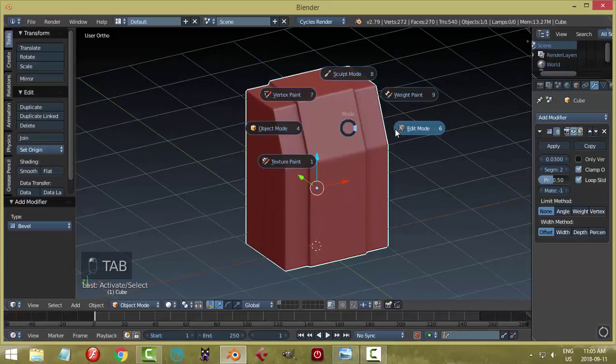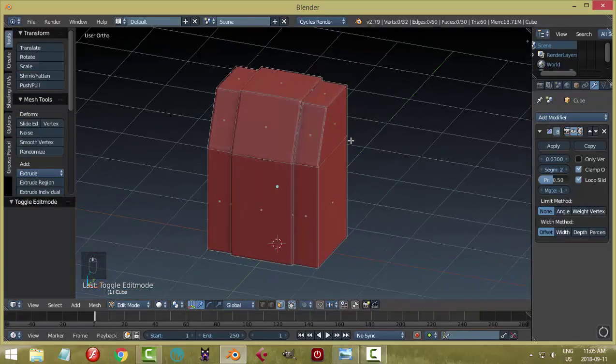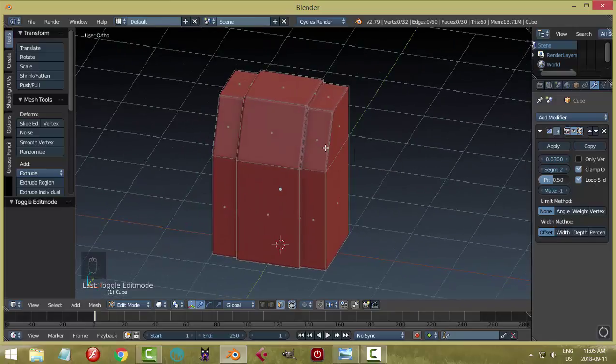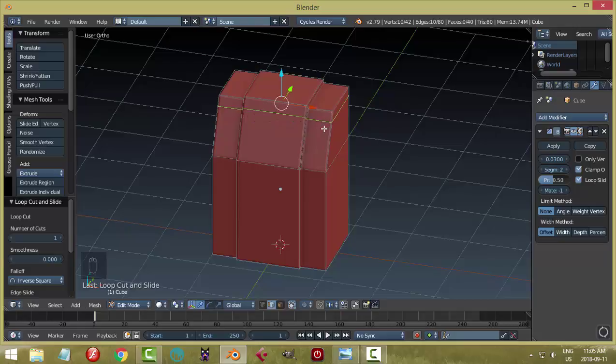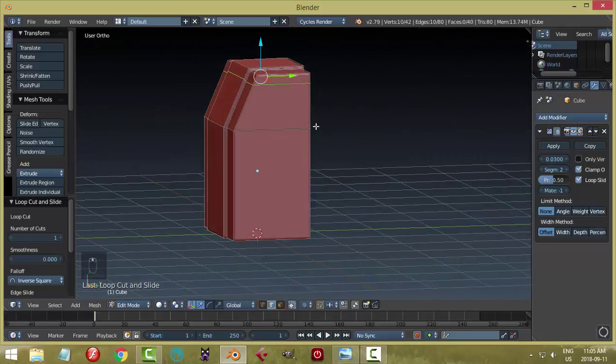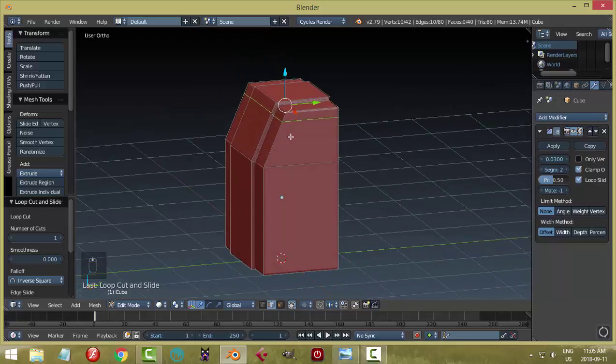So the way I'm going to do this is go into edit mode, and let's decide how to do this best. Well, we could try with edge loops. Let's try this. Let's go Control R. Now, if I click and then I move this, I probably should be looking from the side, but I just want to see how much this will. It won't really change the curvature by doing that. But if I click and I now wanted to change position of that, watch what happens.